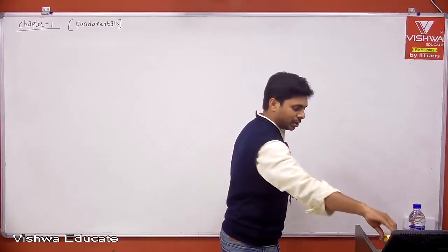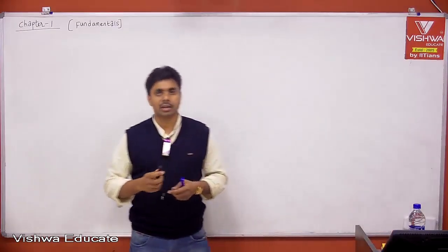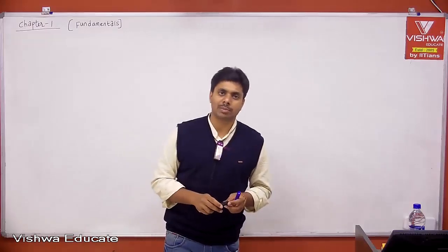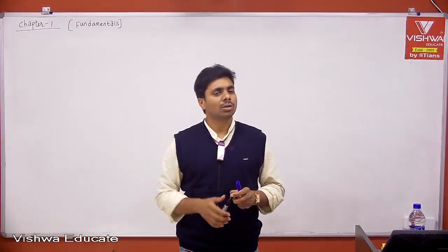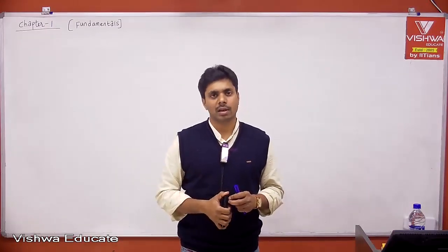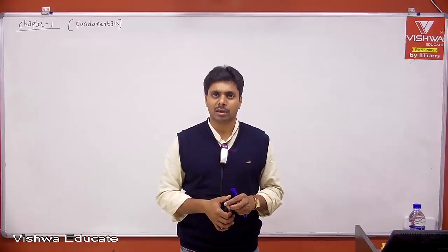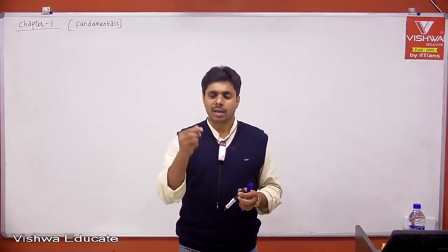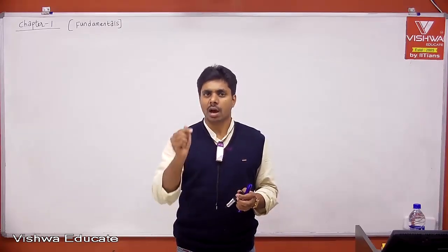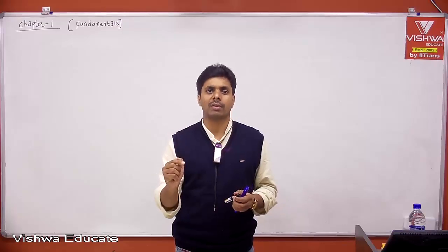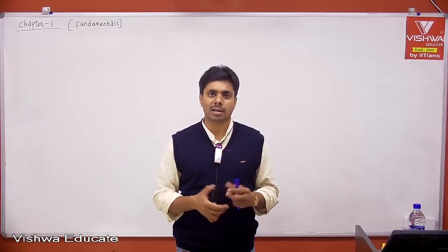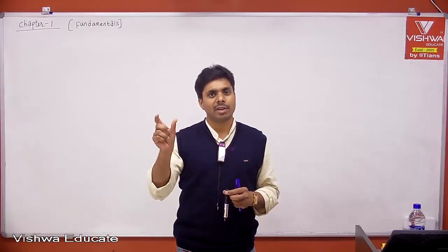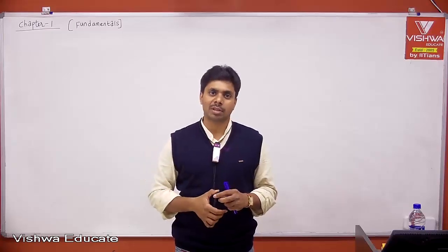Now, let me give you a generic relation, static definition and dynamic definition. Remember, it is not only for resistance. See, what is resistance mathematically? Voltage by current: static voltage, static current, or a voltage V1 and then I1. That is what is resistance, or static resistance. And delta V by delta I, that is nothing but dynamic resistance.